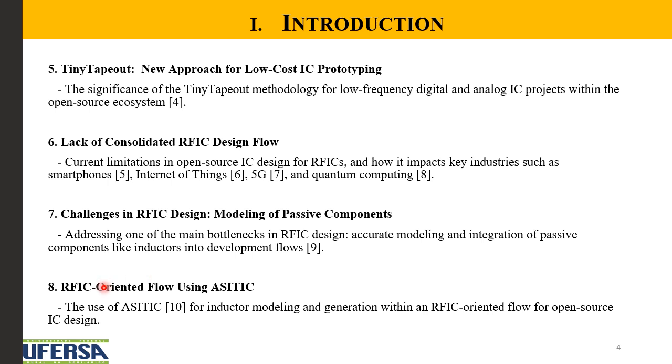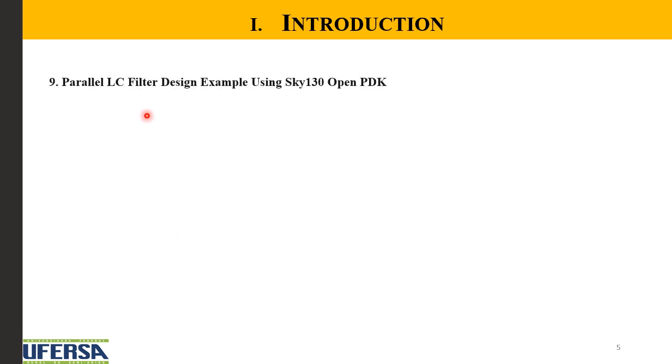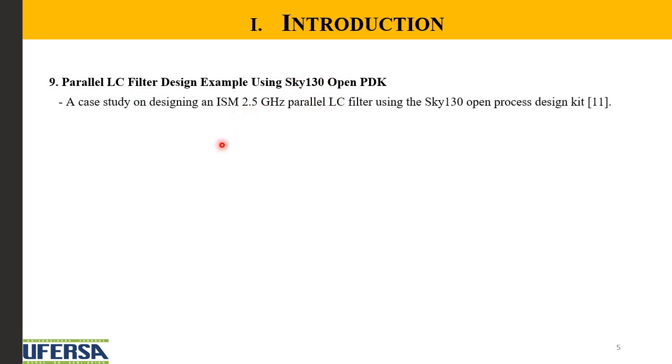So this paper proposes an RFIC-oriented flow using the ASITIC to model the inductor, and this inductor will be inserted into a parallel LC filter using the Sky130 open PDK to operate at ISM 2.5 GHz.